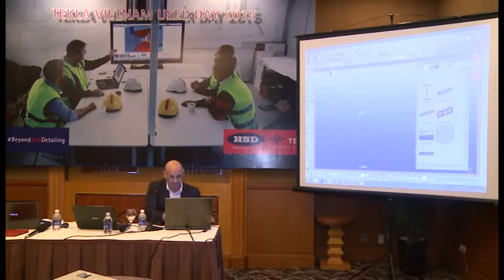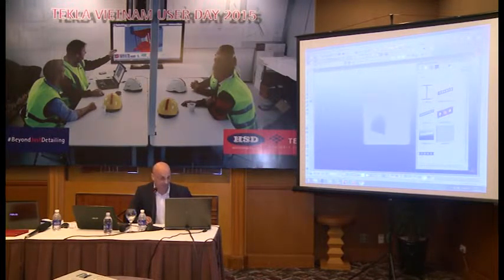Oh yeah, direct modification, that's where I was going, wasn't it? With the direct modification, where I can pick up the different plates, again, remember, Control D turns it on, Control D turns it off. So it's very easy to go from one to the other. Now if I put in here, let's say, a construction circle, so we'll just go modelling, create a circle, just using the centre point, nothing, no big deal. Just something very quick, and we'll put it there like that. So it's a construction circle.